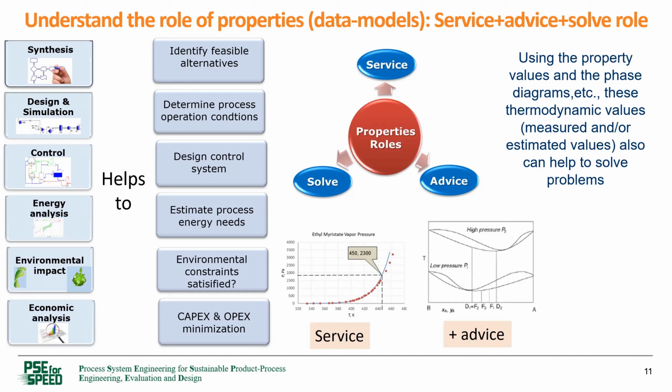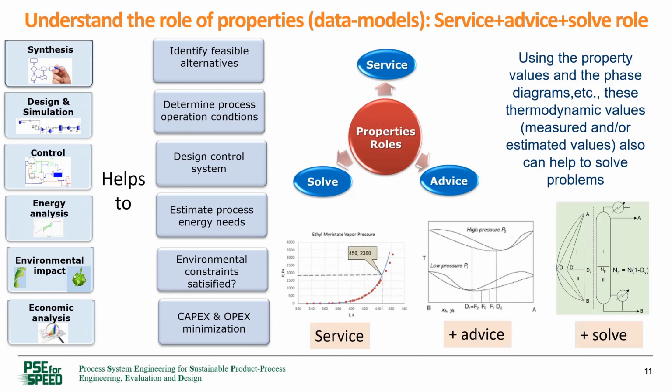Can it help us to solve the problem? As you have seen in webinar 1.2, if we convert the phase diagram, the PTXY diagram, into a driving force diagram, then that driving force diagram will help us to find the optimal design of the distillation column without actually doing too much calculation and optimization.